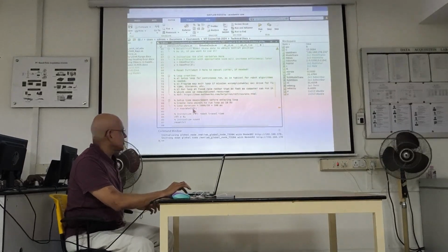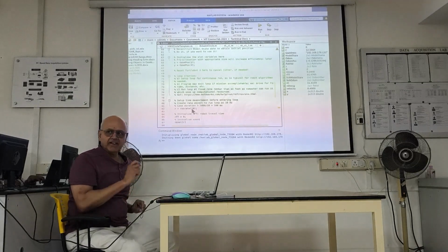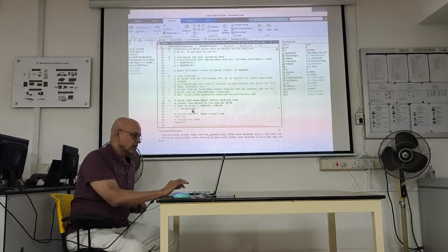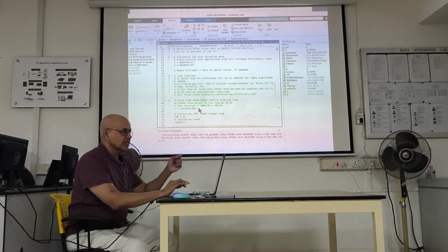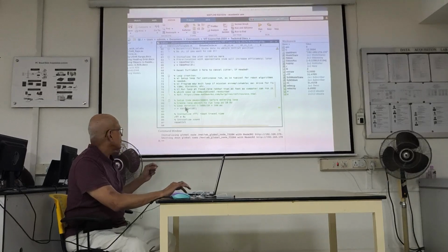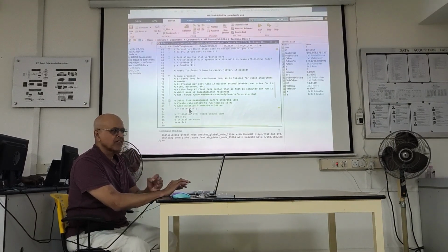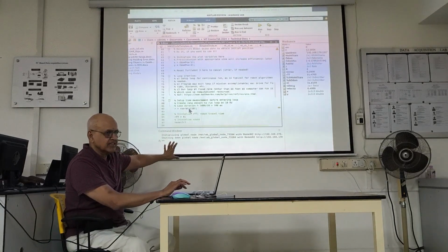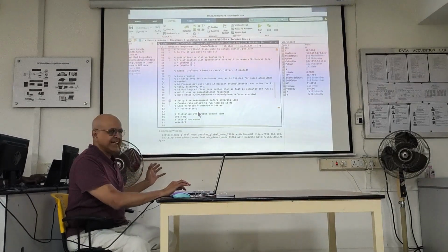And then I introduced you to this technique of running the loop at a fixed rate, not running it as fast as your computer can run it. Because in real-time applications, it's never a good idea to run a loop as fast as you can run it. If you run it only as fast as is needed, the rest of the time is available for you to do other parts of the MATLAB program. Here we're not doing anything else, but it's just a good practice to run the loop at the rate needed.